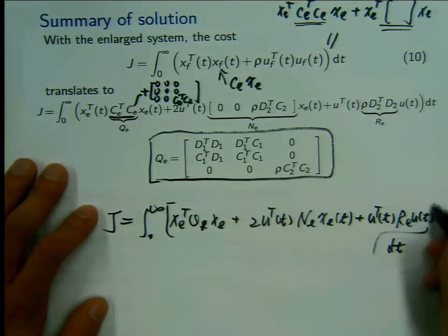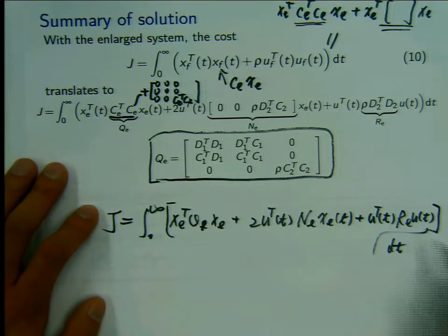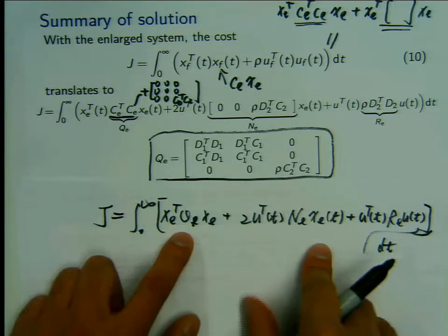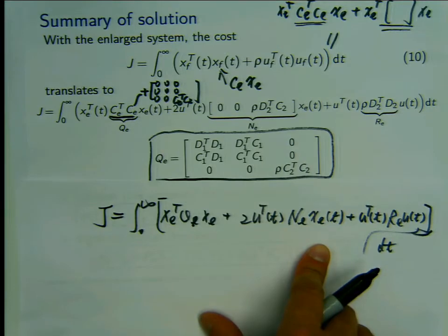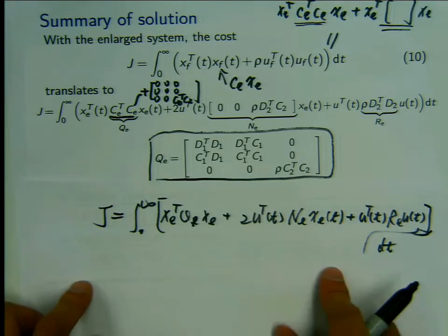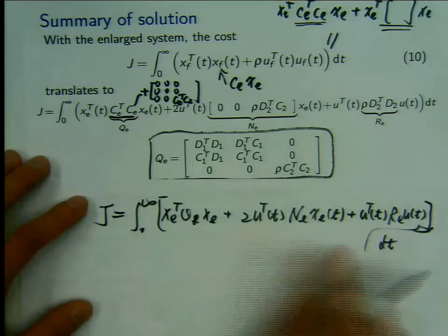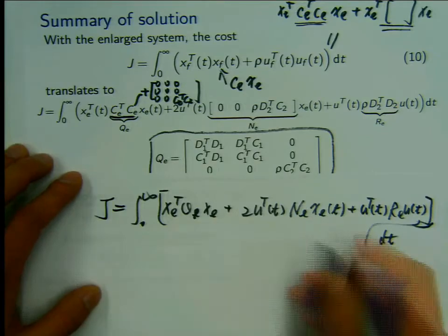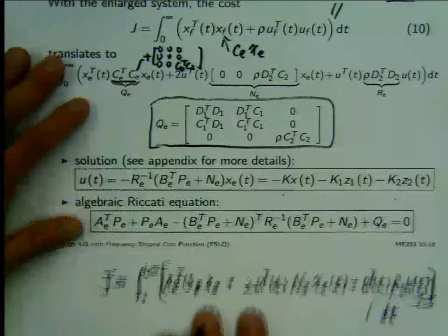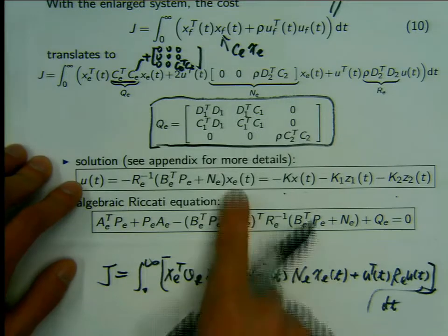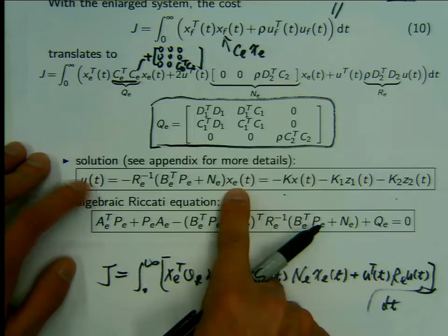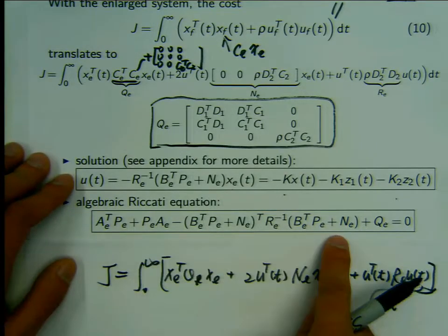If you recall homework number 1, I think, you remember doing a discrete time version of something that looks like this, the optimal tracking problem, and you used dynamic programming to solve that problem. So you know it has an optimal solution. As a matter of fact, the optimal solution looks like this guy. It's still a state feedback optimal control law. So we're using the state XE here, and we have an algebraic Riccati equation.